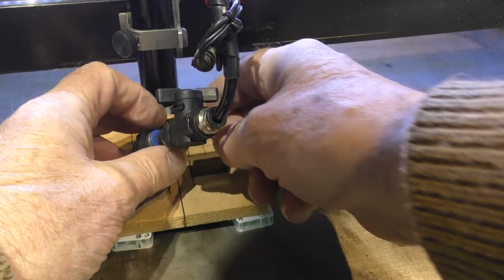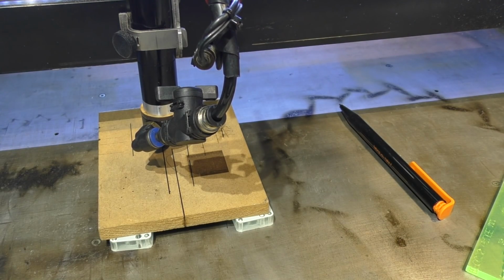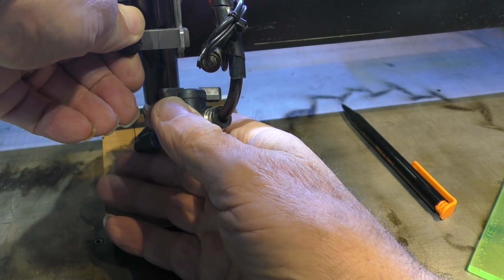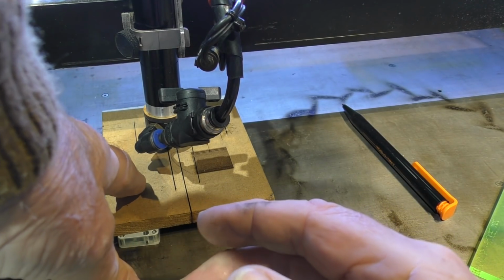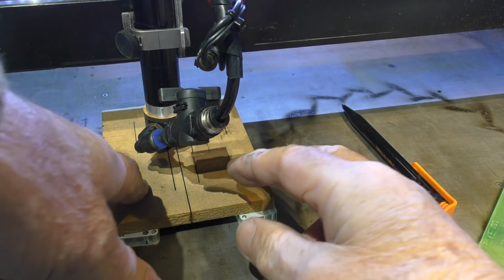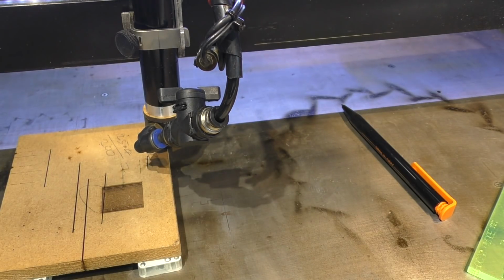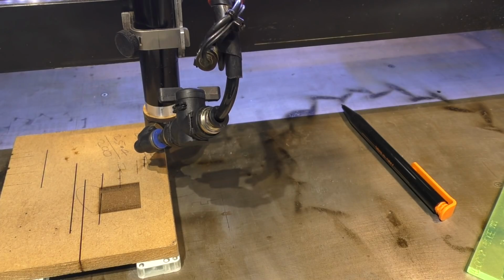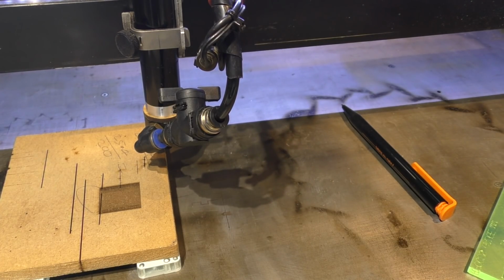What we'll do is just pop this down to within about 1mm of the work surface, which is where it's focused, so that I can get the maximum amount of airflow through the cut. Some 9.5mm MDF here, and what I'm going to do is start off the edge of the cut, and I'm going to run this first of all at full power. Speed to about 5mm a second would be more reasonable for this.